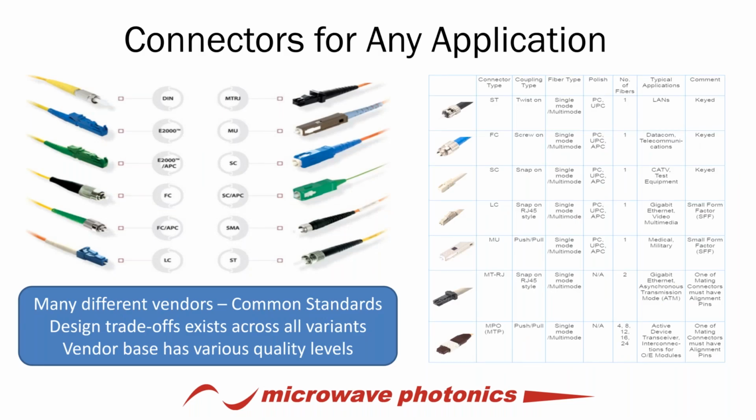There's many different connectors for applications. There's angled connectors, there's multi-termini connectors, there's ones that are more of a snap-on RJ45 style, where there's others that have more of a bayonet fitting. And again, this is a consideration that you would want to think about in terms of what's the deployment environment, what's the density environment, does it look like it's going to be subject to a lot of shock and vibration? You may want to consider different termini or different connectors.